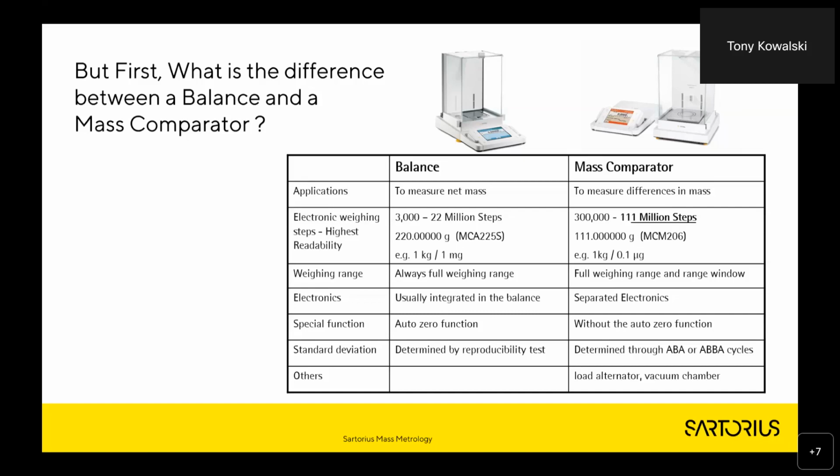And on the vacuum comparator at NPL, we're able to make comparisons in vacuum. The smallest amount of difference that we're looking at on a kilogram is 0.1 of a microgram, and we can't make a correction for air buoyancy that has a lower uncertainty than the difference we're looking for. So the mathematics we can remove by weighing in a vacuum, and we don't have any effects of air buoyancy. So those are some of, or all of, the differences really between a standard laboratory balance and the mass comparator.